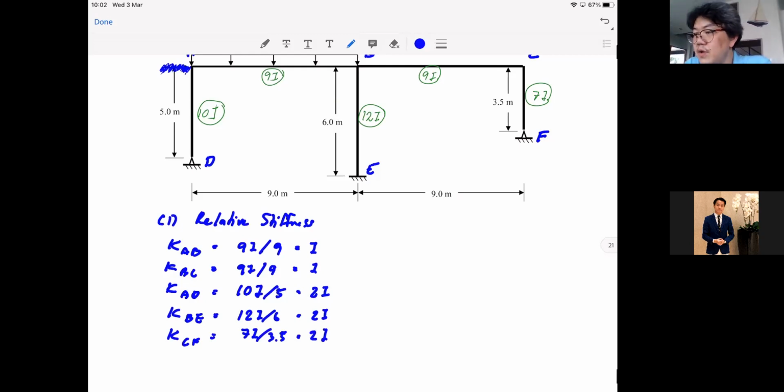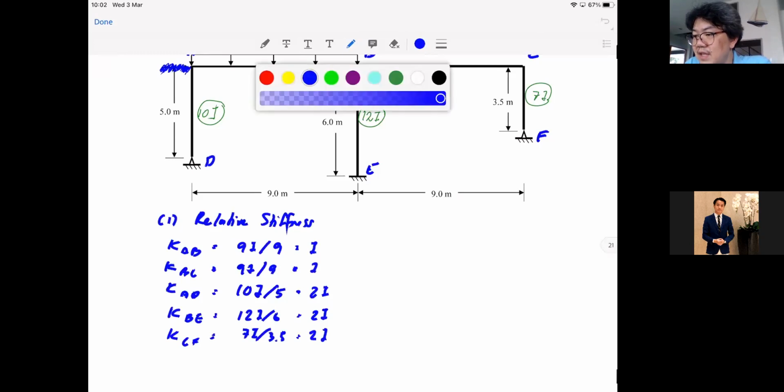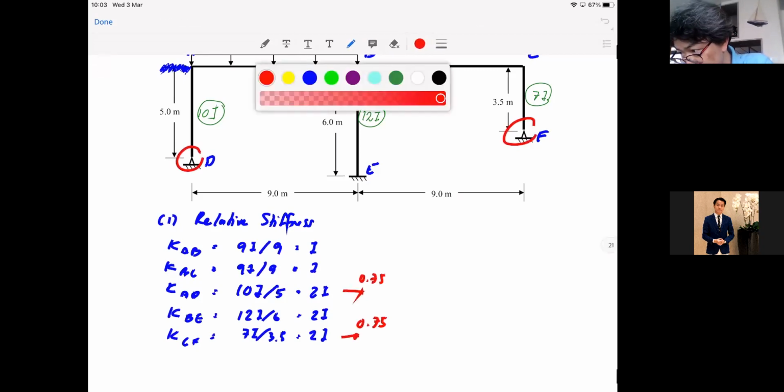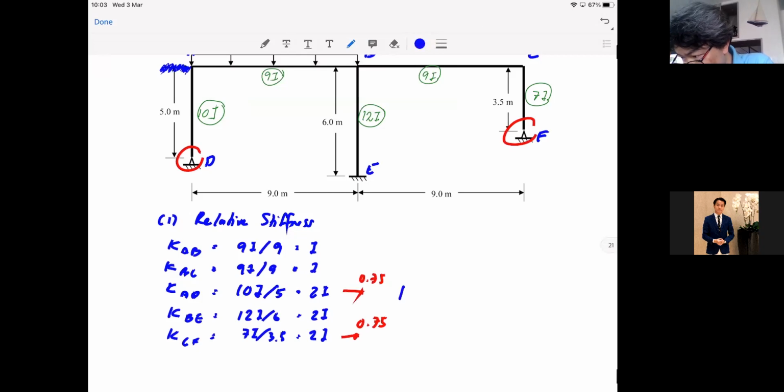But you should know that we have the simple ends here and there. So I have no hesitation to modify it with the 0.75 for the simple end. You may not use symmetry because it's complicated, but you know, when you have a simple end, you really should do it. Use it. Okay. So this becomes 1.5I, and that's also 1.5I.